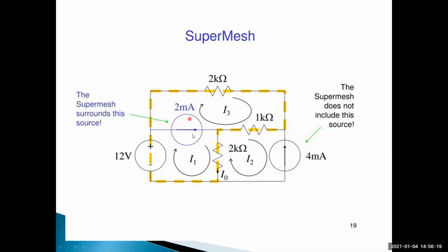And the second equation, I1 minus I3 is equal to 2 milliamps, second equation completed. And then third, that is called the super mesh equation. How to get the super mesh equation? By removing this source, okay, that means it is open circuited, meaning no current flowing in this direction. Just remove this 2 milliamp source. This is the yellow dotted one, so it's called the super mesh equation.